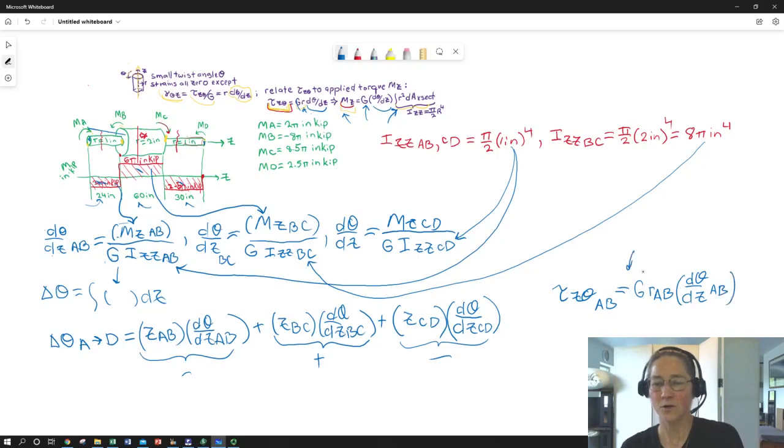So we'll basically multiply by our shear modulus again, which will have the effect of canceling it out of the shear rate. But if we've already calculated a shear rate appropriate for that length of shaft, we put it in, and then multiply by our radius across that section, and we use that to get our shear stress for that section. Then we would do the same for each section.